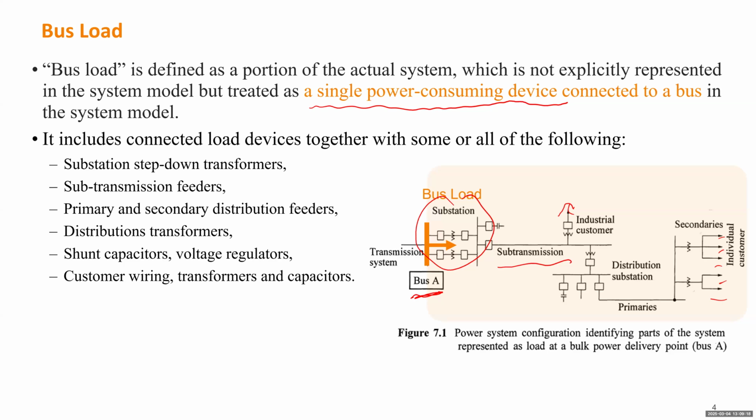You don't have to keep the topology and every element in this list, but you definitely need to consider that any one from this list may change the characteristic of your load. For instance, if you model this bus load to serve the purpose of voltage stability study, any element that can control the voltage and change the voltage characteristic needs to be modeled more accurately.